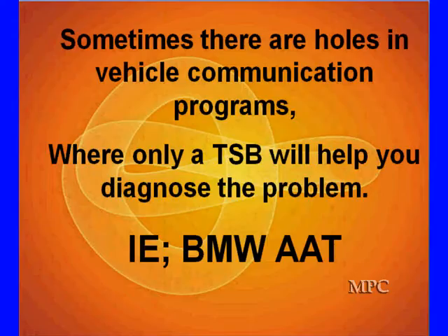We've said it before, we're saying it again. We'll give you a good example. A few years ago, BMW 3 Series. If for some reason the ambient air temperature sensor was disconnected, communications was shut down to the instrument bus. Now you could go and look and do all kinds of testing, and you will never get there.